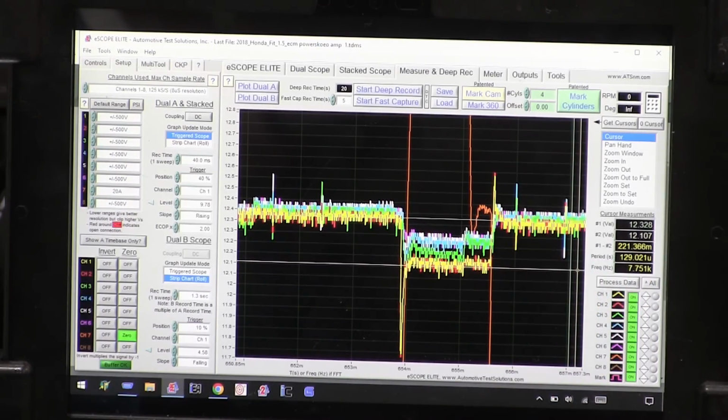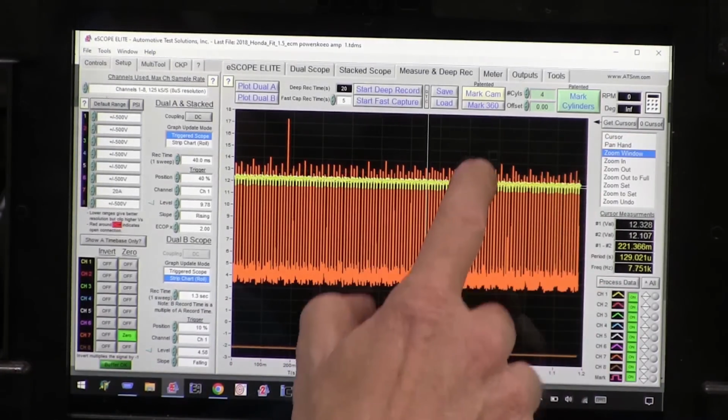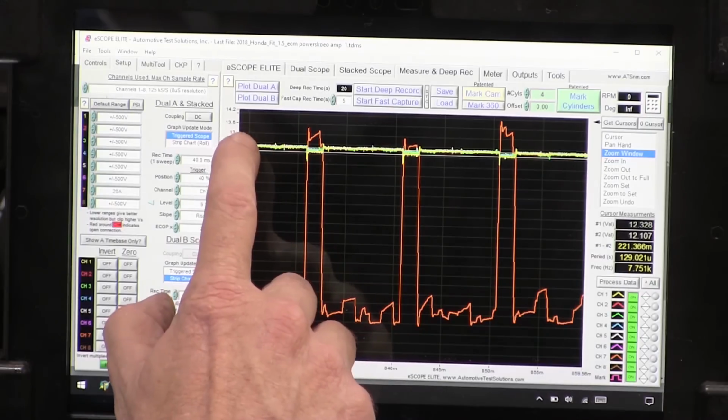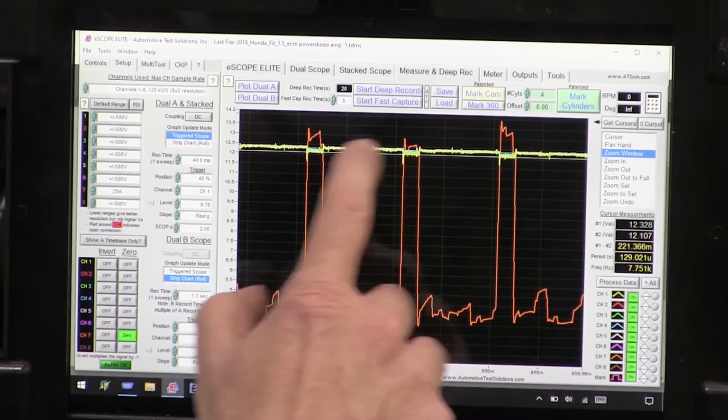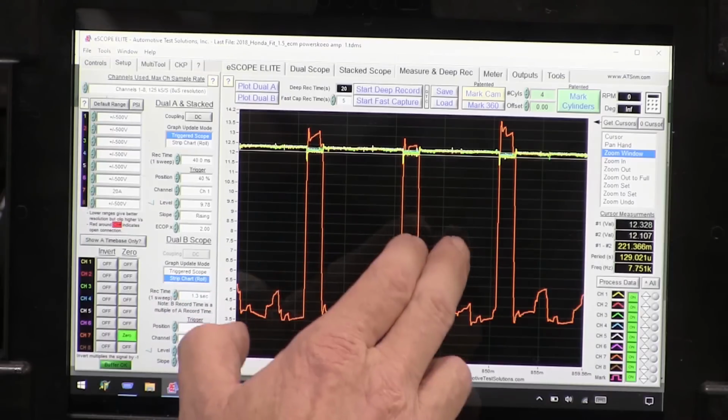So that's not even close to my half volt that I've got leeway on. Basically on powers, I've got about a half volt when I check powers, and I don't worry too much. So my draw is right here. We can see that my draw is 12, 13 amps, but it's definitely steady. It's definitely a steady pulse.